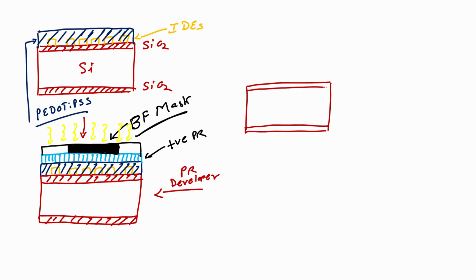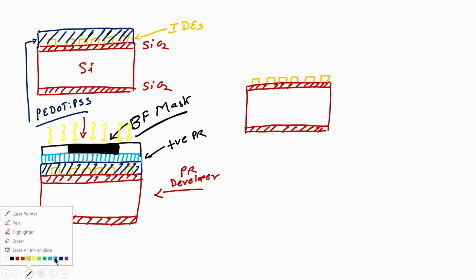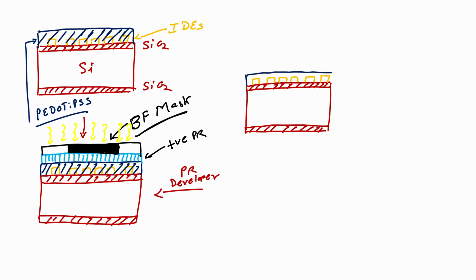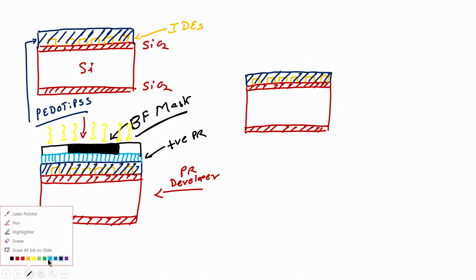My silicon dioxide layer is intact. On that, my chrome gold layer, or chrome gold pattern, the interdigital electrodes, is also intact. On that, my piezoresistive material is still intact, but my photoresist layer will be patterned now.